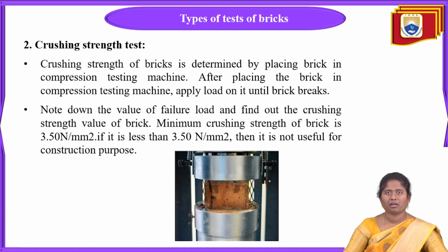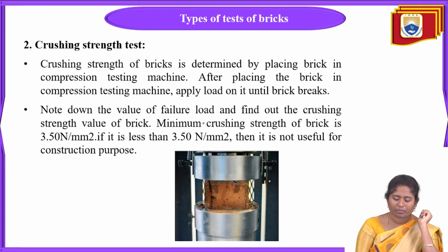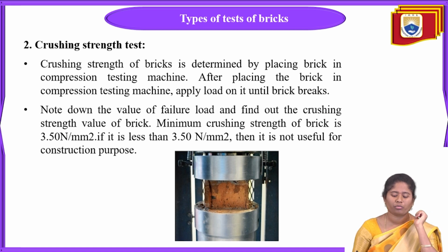After the manufacturing of the brick, we directly take that brick and place it under the compression testing machine. Then we apply load on it, and at a certain load the brick will fail. We find out the crushing strength value from that.